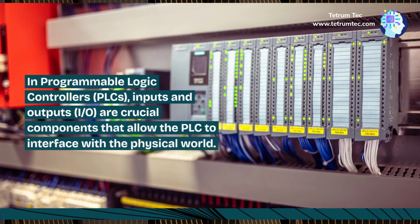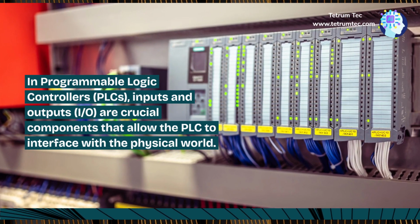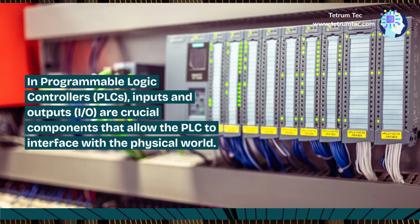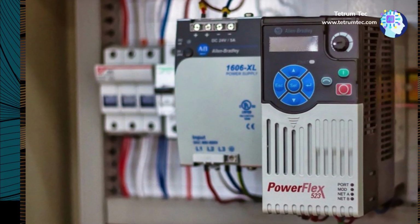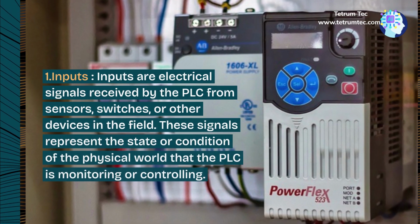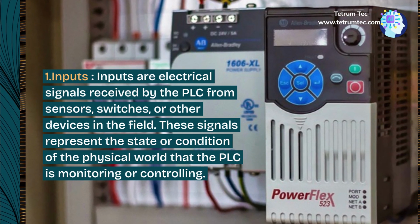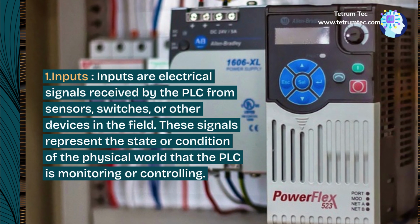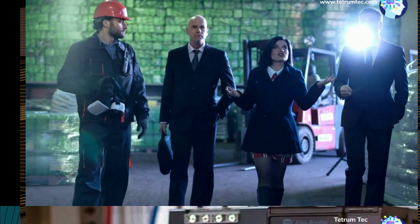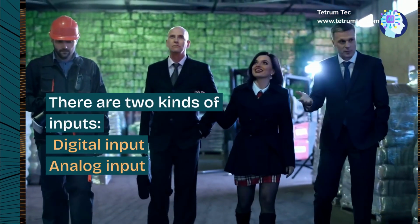In Programmable Logic Controllers, PLCs, inputs and outputs, I/O, are crucial components that allow the PLC to interface with the physical world. 1. Inputs. Inputs are electrical signals received by the PLC from sensors, switches, or other devices in the field. These signals represent the state or condition of the physical world that the PLC is monitoring or controlling. There are two kinds of inputs: digital input, analog input.